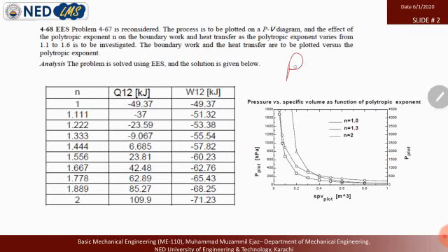As you know, the polytropic process is a general process that is applicable to numerous processes by changing the value of n. The general values of n are: n equal to 1 is isothermal, n equal to 0 is isobaric, n equal to infinity is isochoric, and when n is 1.4, it is adiabatic. By changing these values, you can see that this numerical is solved by the EES calculator for numerous values like n of 1.0, 1.32, and several volume and pressure values.